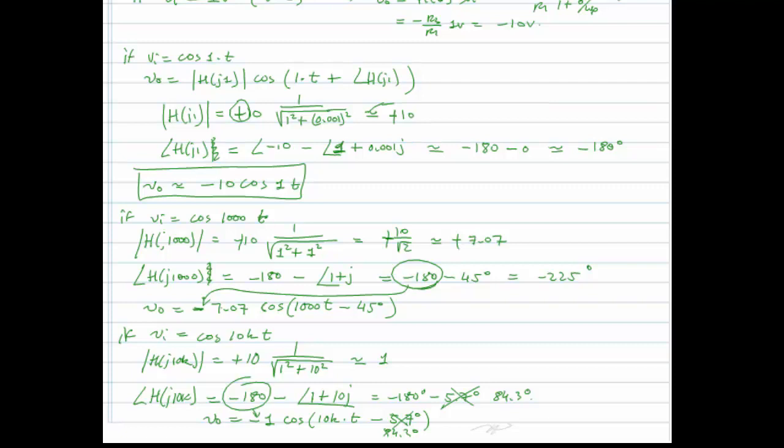So we put in an input that is an amplitude of 1. The DC gain of the op-amp circuit is 10. So down at DC we would expect 10 volt amplitude out. By the time we get to 10,000 radians per second, we're down to a tenth of 10 volt amplitude. If we were to recalculate this at 100,000 radians per second, we would see that we'd be down to 1/100th of an amplitude of 10, so we'd be at 0.1. And at 1,000,000 radians per second, it would be 0.01 and so forth. And so we do have this attenuation here.